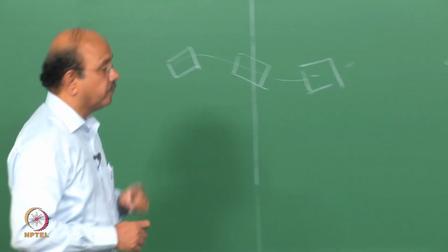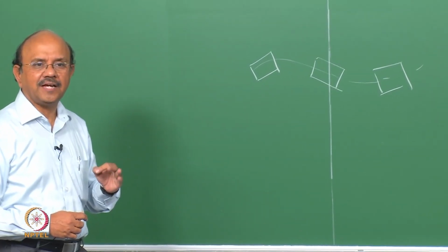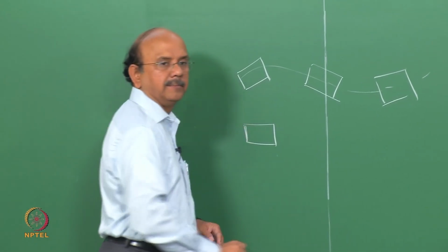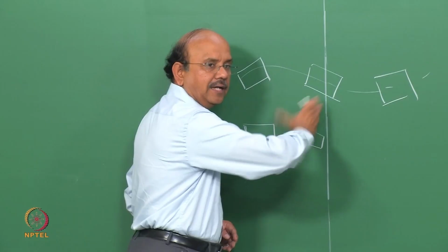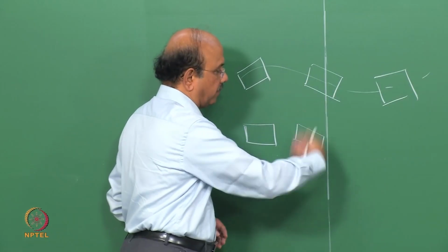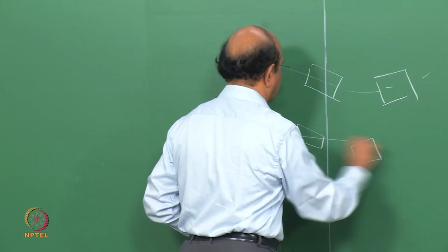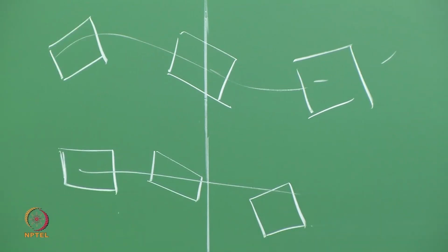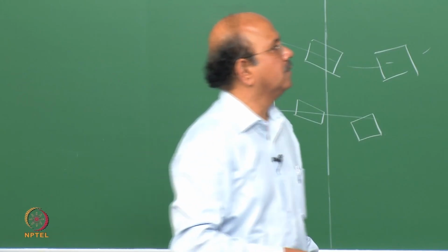The other thing is what we call rear axle stability. If this is the vehicle, the rear slips up and down like that, in a straight line, where the rear wags the tail. So that is rear axle stability. Again, it's a question of oscillation about the rear axle.